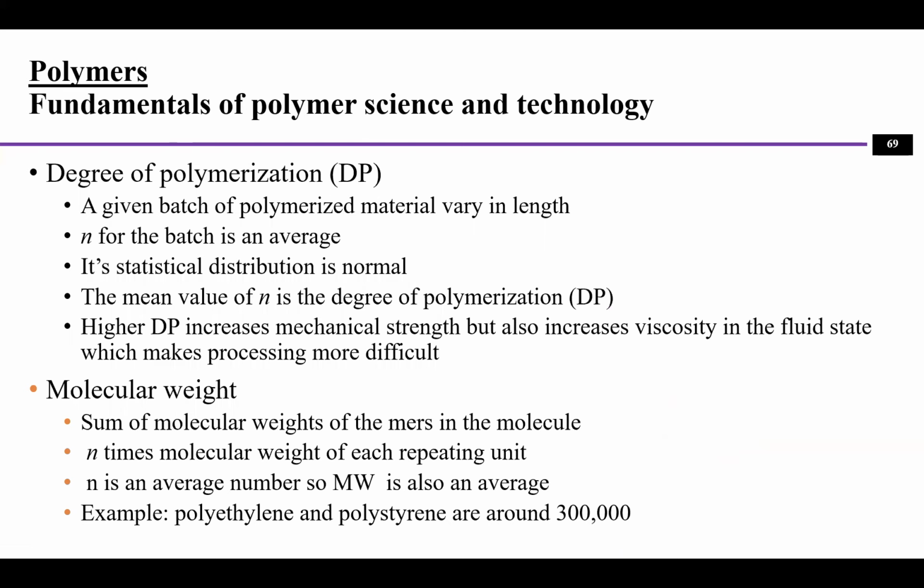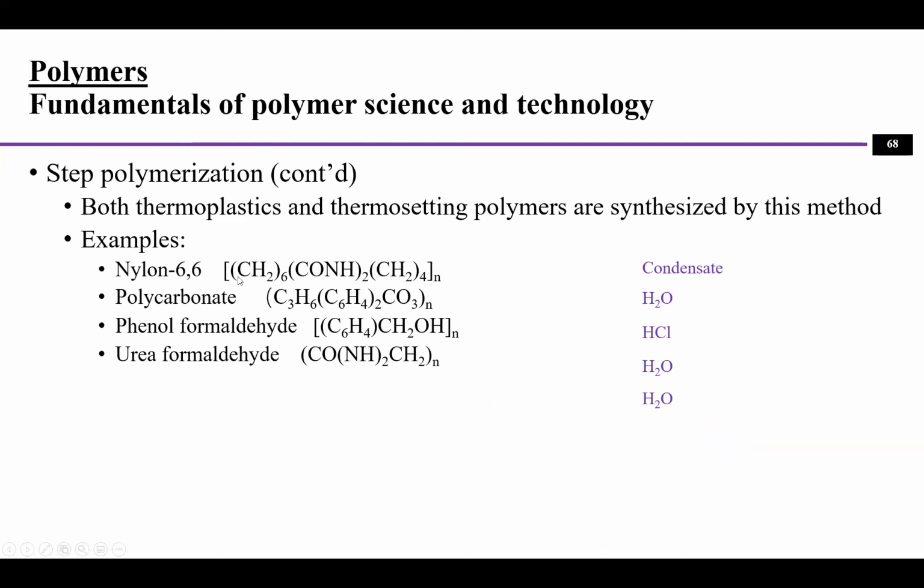And when we're talking about polymers, a lot of times we'll see this n inside, for example, this nylon 66. And inside, this is the monomer, right? What is the unit pattern, right? And this is the mer. And we have n times of a repeated pattern of this structure. Well, the n is really an average number, right? n is really an average number.